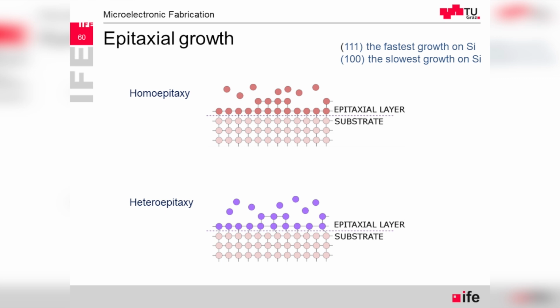The problem with heteroepitaxy is that we have two ions of different elements of different atomic number, for whom the characteristic constant of the crystal is a little bit different. So that creates a little bit of stress on the surface, and actually that's the reason why for creating this stress in the modern technologies, in the MOSFET transistors, the germanium is used is exactly for the stress reason.